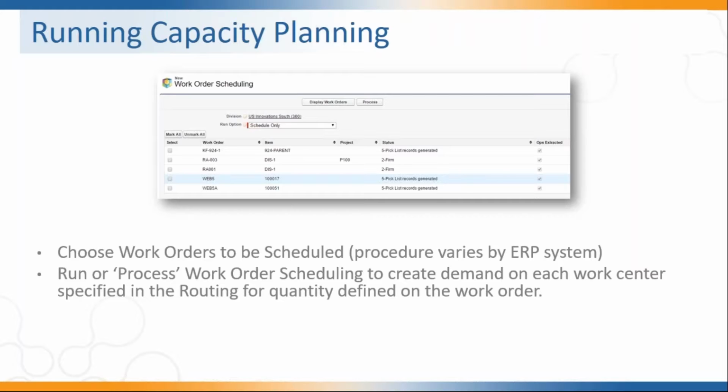You remember, too, that we had 3 kinds of time. We had setup time, run time, and machine time. Setup time would be the time it takes to put the machine together to handle the job that must be done, to set up the machine with the tools that are required, and so forth, so that the user would be able to then use that machine and do all of the pieces that have to be drilled or welded or whatever has to be done to them.